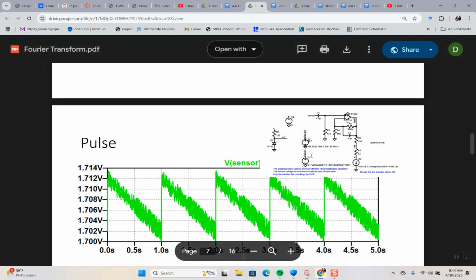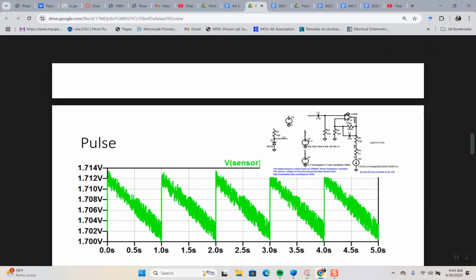So it's blocking the DC signal, but then on the feedback loop, you've got a low pass with some gain. It's a little bit tricky because this is not inverting compared to this. The circuit's a bit of a hack. They combine things, and then this is the LED driver, and what it does is turn it into a square wave that blinks an LED on and off.